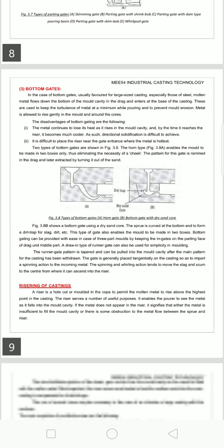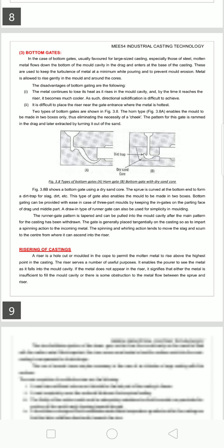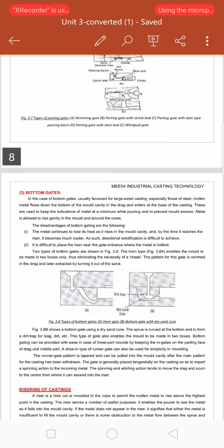It improves solidification and minimizes sand expansion. Then iron oxide, about 0.2 to 0.8 percent. Fine dust of iron oxide improves hot strength. Dextrin, of vegetable origin, a very fine powder, improves dry strength, up to 2%. Molasses, up to 10%, improves edge hardness. Boric acid and sulfur improve surface finish and prevent metal mold reaction. All these are the advantages. So all these are the additives added to the molding sand.